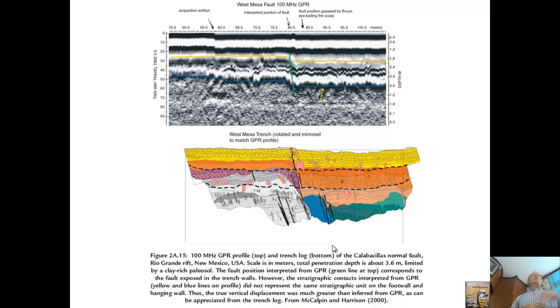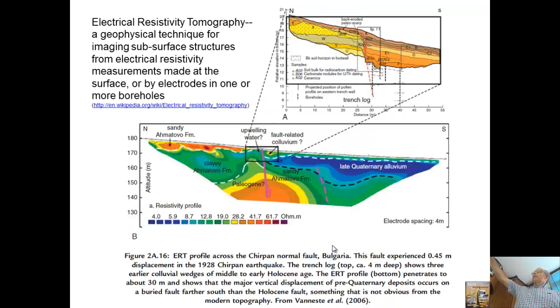Magnetics, geomagnetics sometimes can be really good. They almost always are easy to do. Most magnetic surveys are fast. And so you can also make a geomagnetic map of a site, and what that does is give you many observations. And so then if you do a map of the magnetic signal, you may identify some big sources at depth that show where the fault zone is. So the magnetic studies I would put in this classification also. It can work pretty well. For ground-based magnetometer, you can also do airborne, like airborne gravity or airborne aeromag.